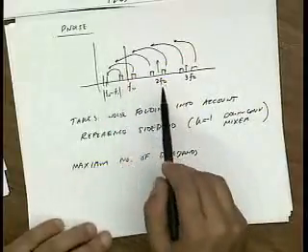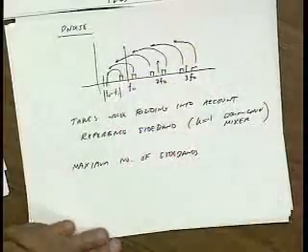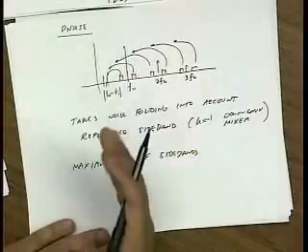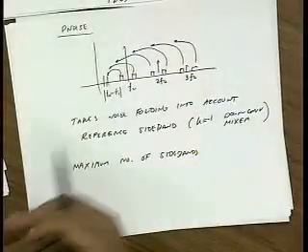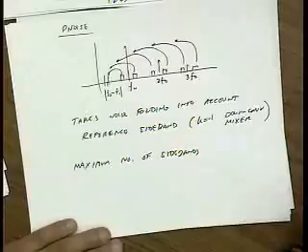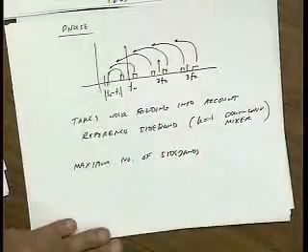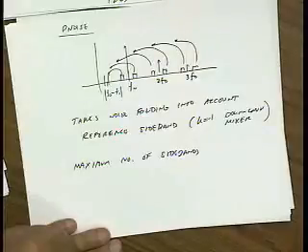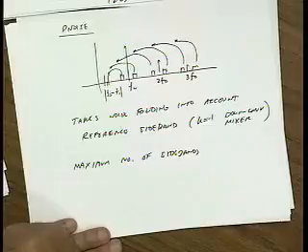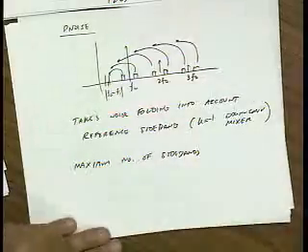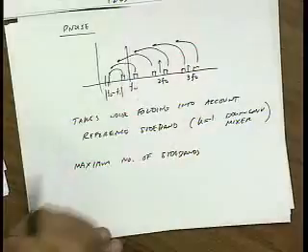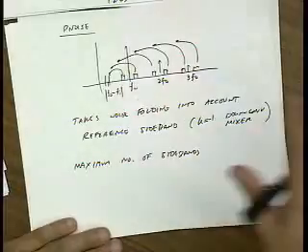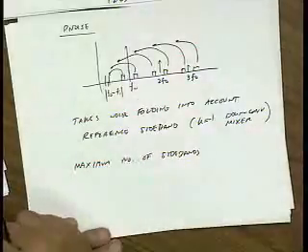So what it does is, you tell it, take 50 sidebands into consideration, right? Usually that's pretty good. But the more sidebands you specify, the longer it takes to do the noise calculation. You basically pick enough sidebands until the answer doesn't change, right? So if you're really interested to know how much noise folding is going on, you could start out and say, just include the noise from the first sideband. Then you could say, now add the second sideband and the third sideband, and you'll see the noise figure go up step by step.